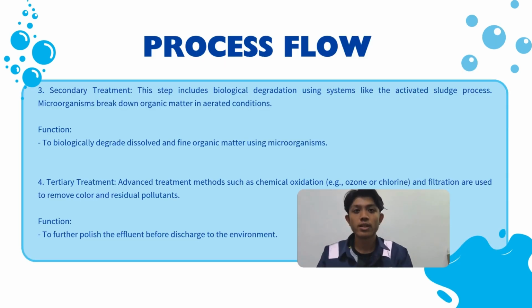For the secondary treatment, this step includes biological degradation using systems like the activated sludge process. Microorganisms break down organic matter in aerated conditions. The function is to biologically degrade the soluble and fine organic matter using microorganisms.